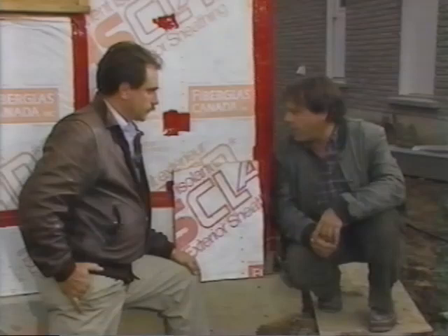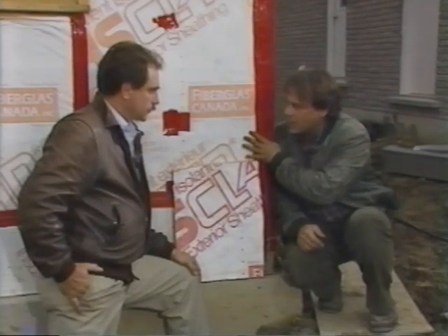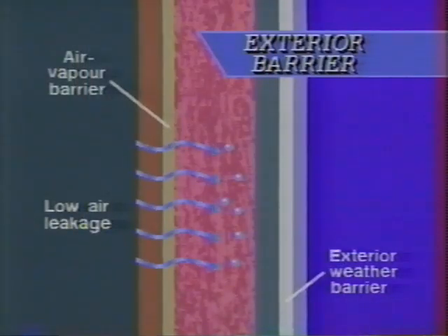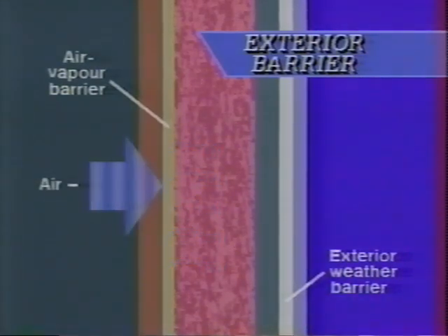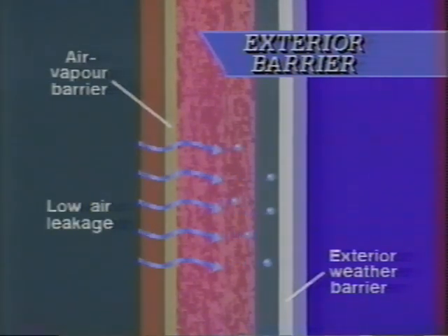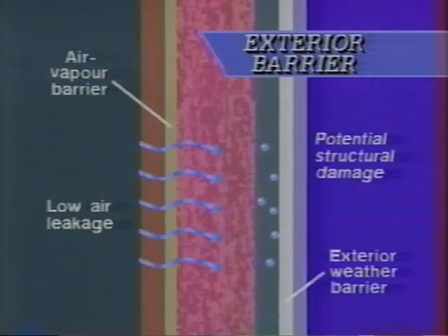So, you want to prevent moisture from being trapped on the inside of this wall assembly. The general rule is that the outside shell of the house should be looser than the inside. If the interior air and vapor barrier is effective, there should be no problem with the use of any vapor-resistant sheathings. But the key is that the inside be tight. Now, some real problems arise where the exterior part of the wall is tighter and water vapor gets trapped in the wall cavity. That makes eminent sense. Now, what do you do about that?